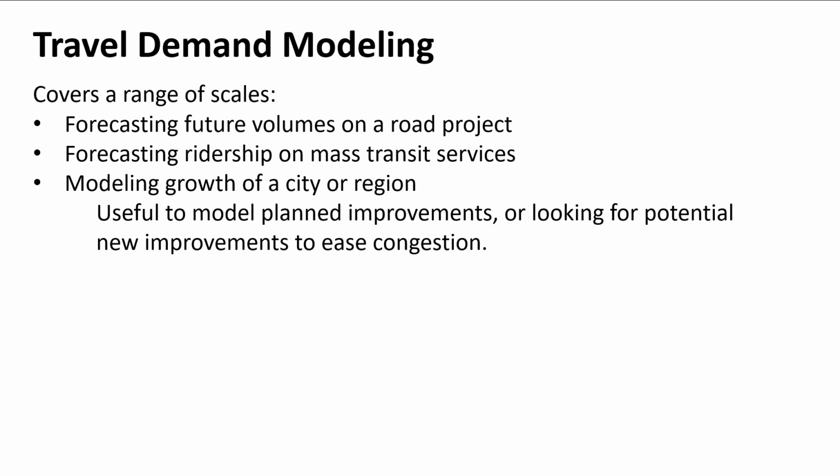Right. And it could be as simple as, well, we know traffic has been growing. We look at the last few traffic counts out here, and it looks like over the last 5 years, we've had a standard growth rate of 1.5%. So we use that 1.5%. We project it forward 20 years. Right? That's one way to do it.